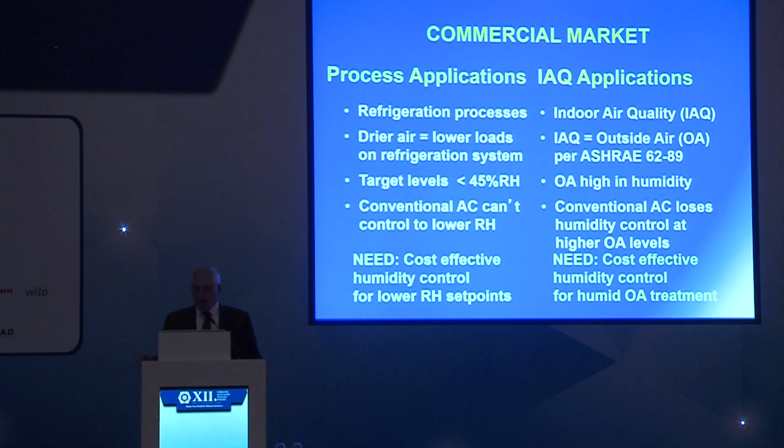On the other side, in the commercial market, there are indoor air quality regulations. In other words, if we have to bring in outdoor air for ventilation, many times a desiccant system is used as a standalone system to pre-treat that outdoor air and bring it into the space at least at space-neutral humidity conditions, or a little bit below. So we're taking humid outside air, pre-treating it, taking the water out, and then introducing it into the space as ventilation air.